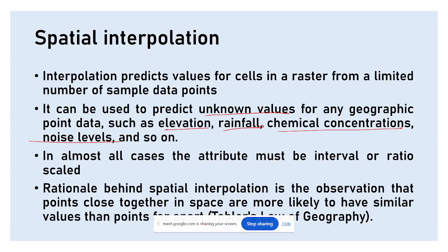Before you plan for the survey, you take a look at the area and decide some strategic points. It's not like you're randomly going and collecting. You choose some strategic points according to your requirement, and then using the data generated from those points, we will interpolate.